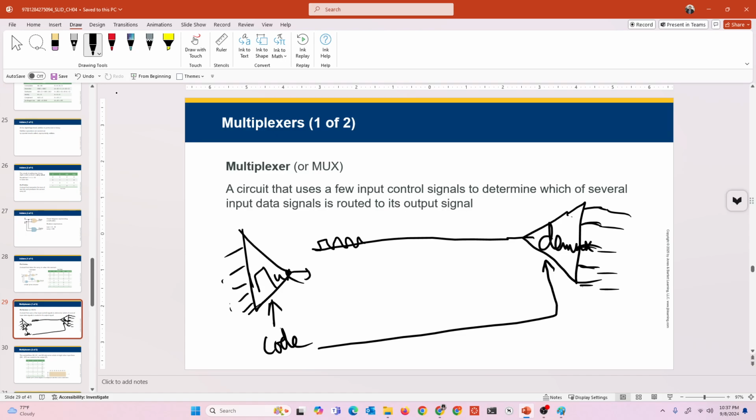Okay, why? Because if you use a wire for 5 miles, for example, this wire has a resistance. If it starts with 5 volts here, now here it is 0.1 volts, because the resistance will attenuate the voltage and the signal is completely gone. If it was a 1 here, that 1 is now 0 on this side.